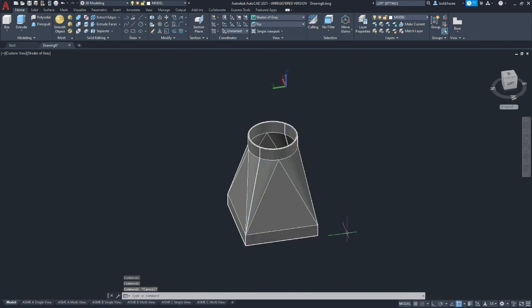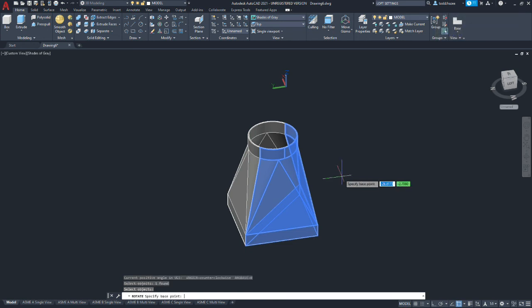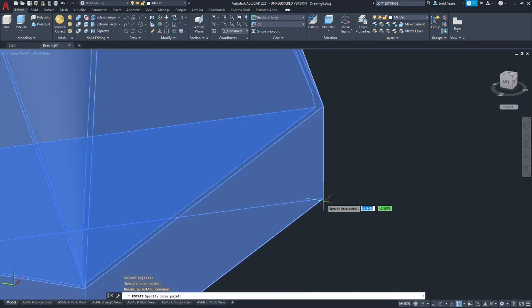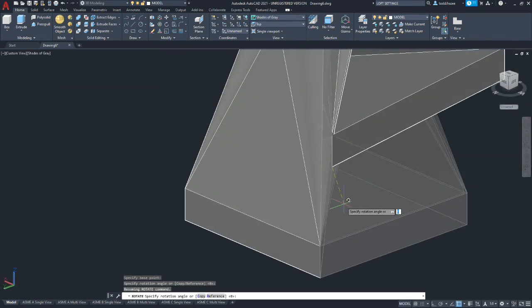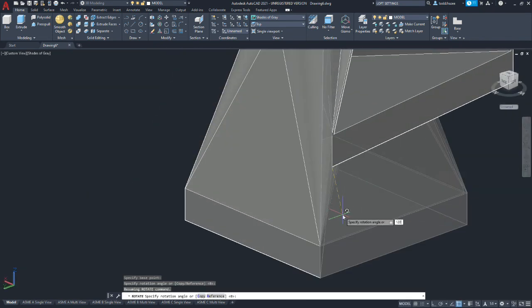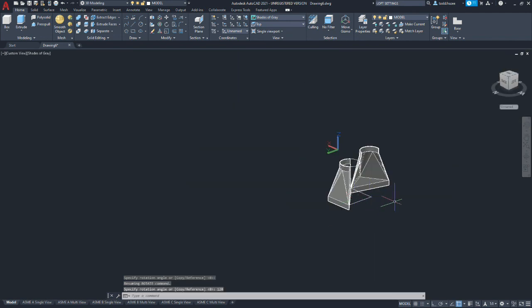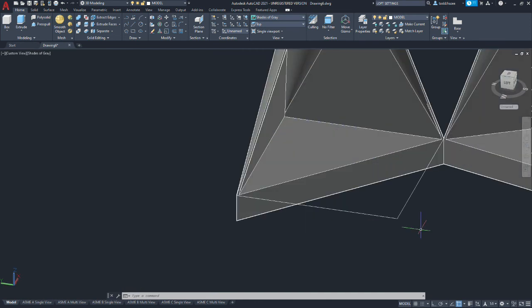Now we need to do a rotate command. And you need to make sure you're still on the top view when you do this. And we're going to select 1/2. And we're going to accept that half, and we're going to rotate about one of the back corners. And let's rotate it 120 degrees. And that should give us a good shot of our part.